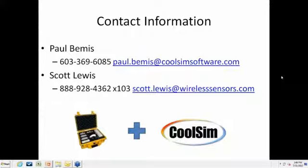Another question to you has to do with location of deployment. How important is it, and how do you know where to put them? Yeah, that is a good question. We get into that dance quite often. How many do I need? Well, how many do you want? And so we kind of try to break that cycle with what I introduced early on, which is the rack pack. We say, place to start is to instrument the top, the bottom, and the middle of every third rack.